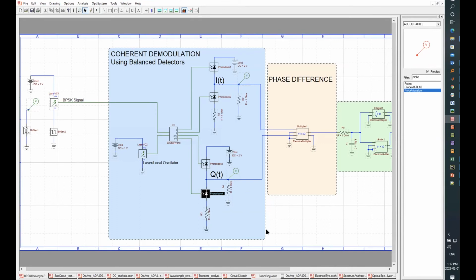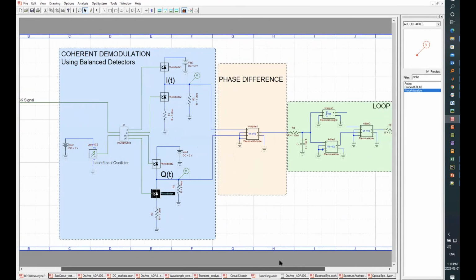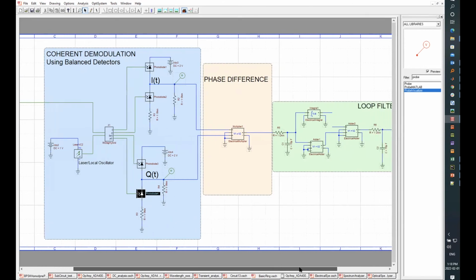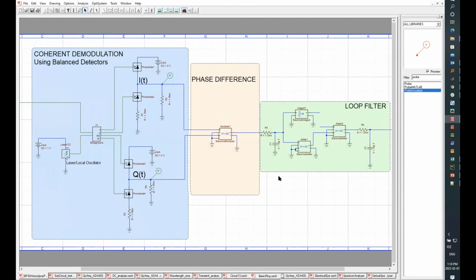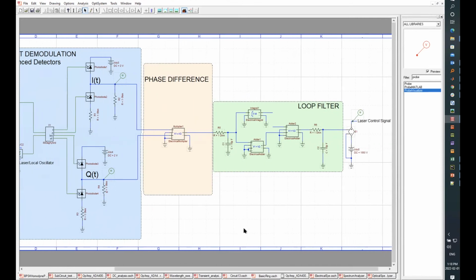What we have done after the demodulator, so normally you would take your I and the Q signal, and then you can do whatever you want with it afterwards. But here we used a detector circuit and a controller circuit in order to control the frequency of the local oscillator. Because if the local oscillator and the incoming signal are not locked, not the same frequency, the I and the Q signals are going to start rotating, which then makes the ADC, analog to digital, almost impossible. You're either going to have to do the correction using an analog circuit like we're doing here, or